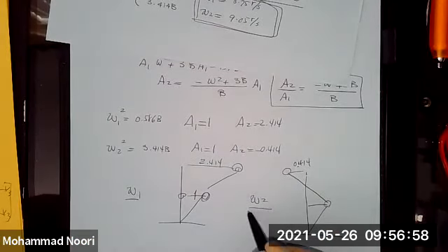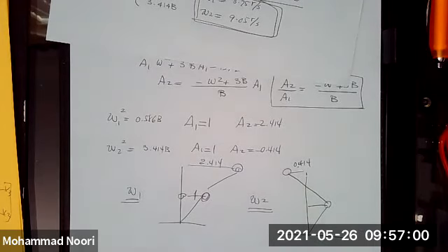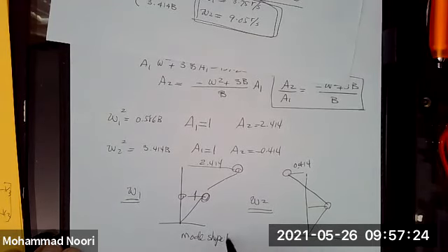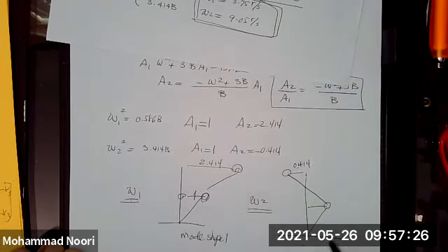So for the free vibration of undamped 2 degree of freedom systems, we can find the natural frequencies and the corresponding qualitative shapes of deformation for each frequency, which we call mode shapes. So this is mode shape 1, corresponding to frequency 1, or the fundamental frequency.